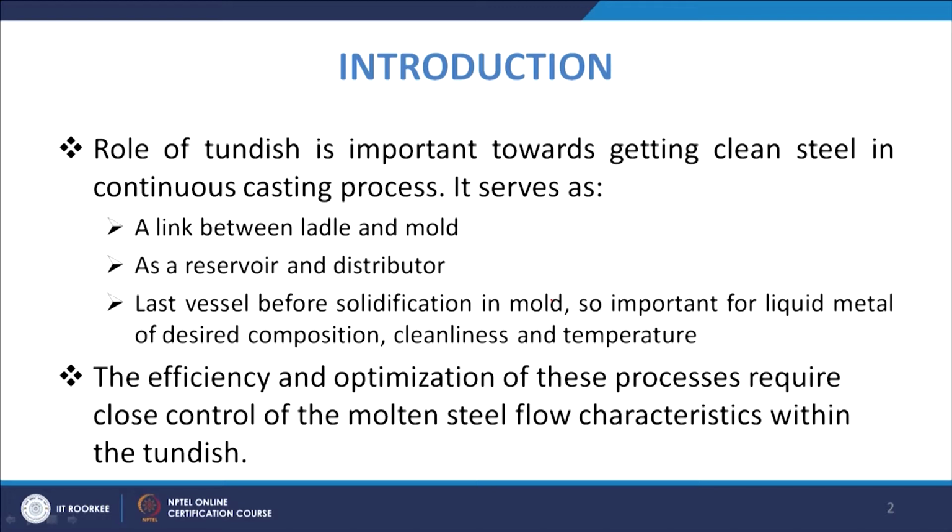Another reason why the tundish is important is that it is the last reservoir before the metal enters into the mold. After that, the metal going to the mold has to solidify, and if the liquid has any kind of issues, those issues cannot be addressed. So, whatever issues are to be addressed, like inclusions needing to be floated, or the temperature having to be adequate, all that is to be seen in the tundish itself.